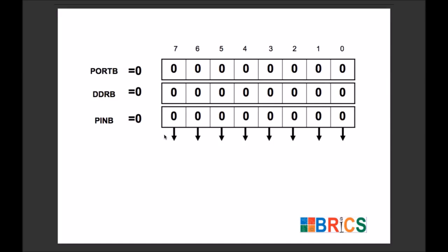So whenever we want to connect some external device, we can simply connect one LED to one pin like this. I have connected one LED to this pin. So this LED will actually get connected to the register called PINB, and we know that we can't write something on PINB directly using the statement PINB equal to something. So to write something on this bit, we actually need to get help from the top two bits, the DDRB bit and the PORTB bit.